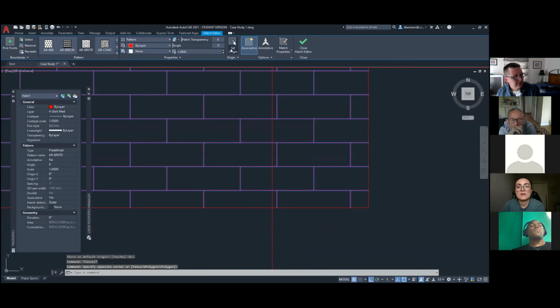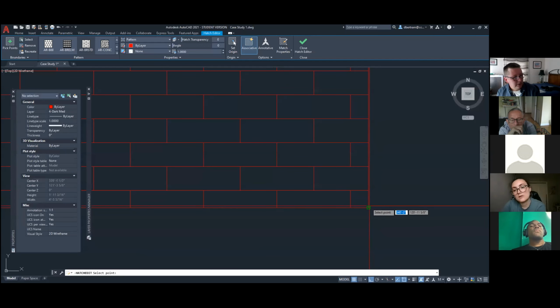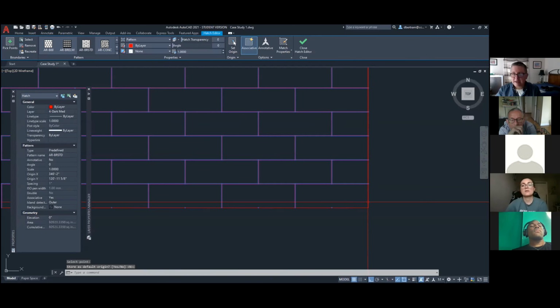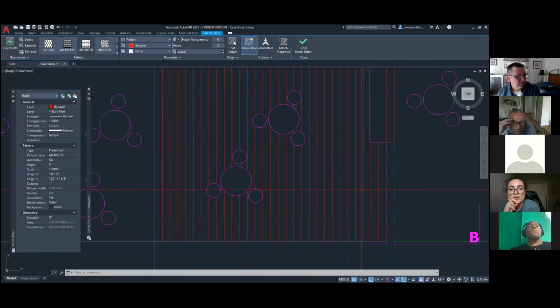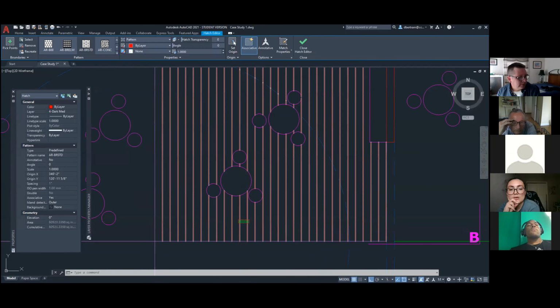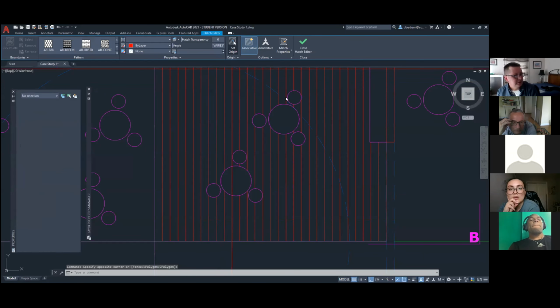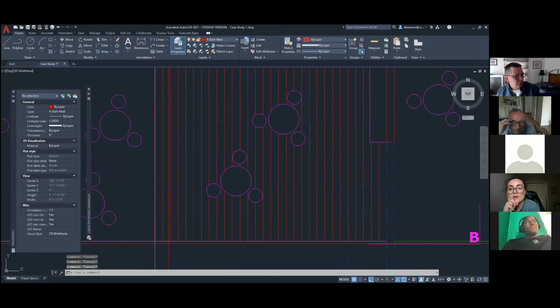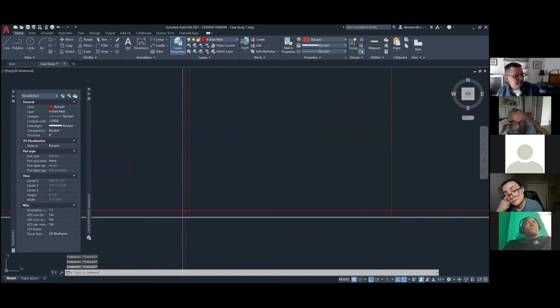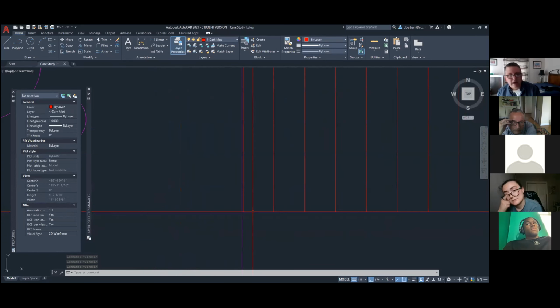So select set origin, and that's where the whole hatch goes out. That's the origin of the hatch. So bricks, cinder block, CMU, cinder blocks, very important. And this is less important, but you can see the difference still. Set origin, if we move it to this side, here it's just a visual thing, really. You could get away with it wherever you set it, but if you're not liking the way it's aligning, that's available.